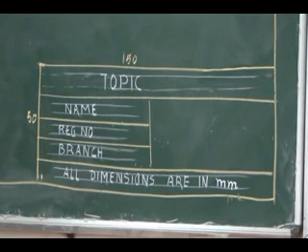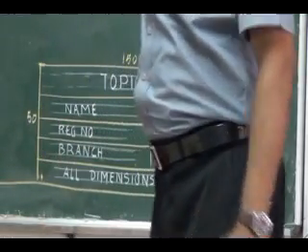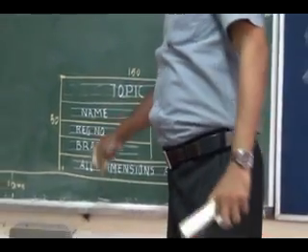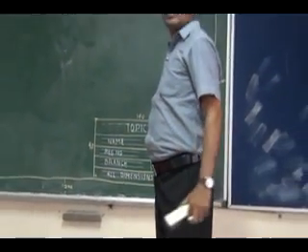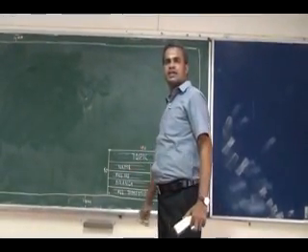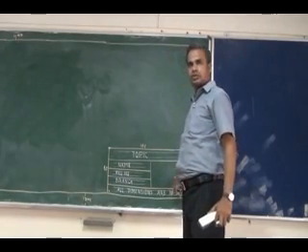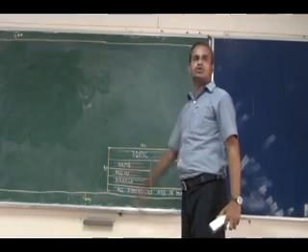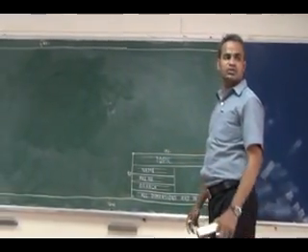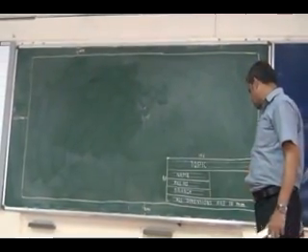So now this is the title block that you are going to draw in your drawing sheets. Do you have any clarification in this? It is very clear now. Title block is 50 by 150, and it will have a 10 mm box inside. Here on the right side you will have a separation. This is a space used for showing the symbol of the drawing. Any drawing, you can see the projection symbol will be there. That you have to draw here. I will come to that.